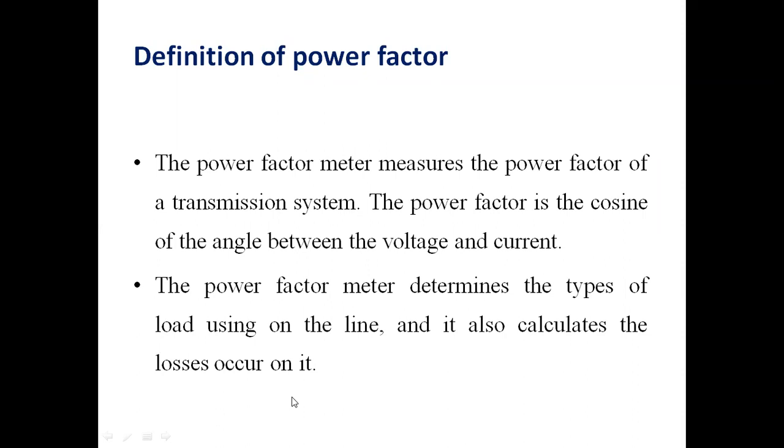The main objective is to measure power factor. The current coil carries the current to measure power factor, but the voltage circuit is split into two parallel paths. We will see this further in the discussion. So just go with the analysis. The voltage circuit, or voltage element, is split into two parallel paths. One is an inductive circuit and the other is a non-inductive circuit.